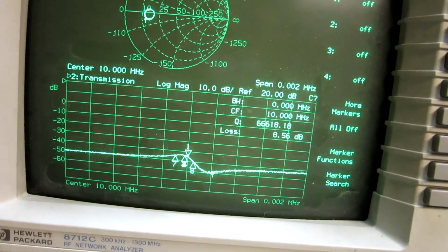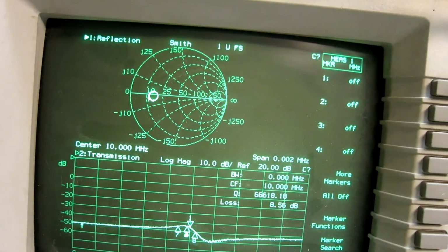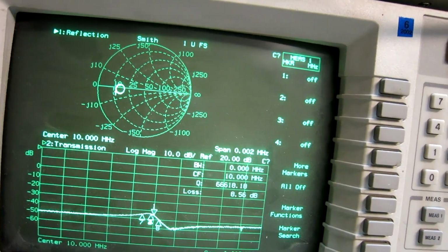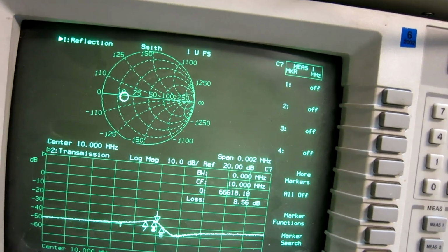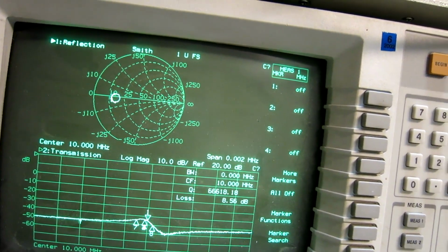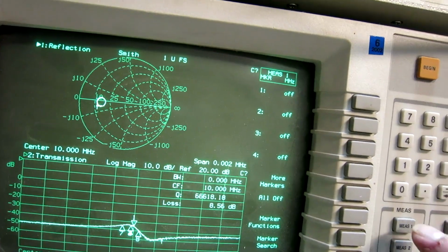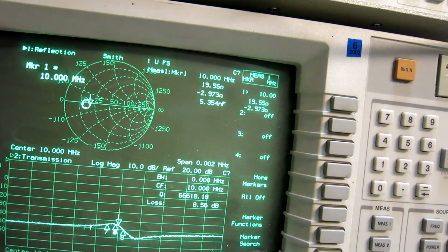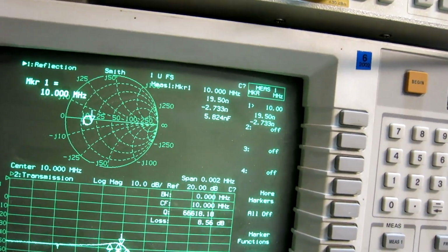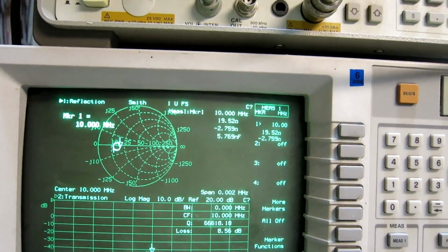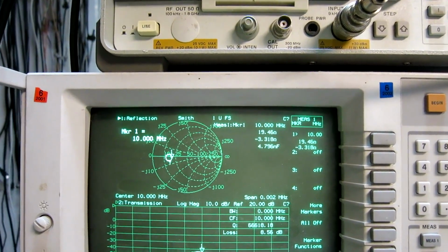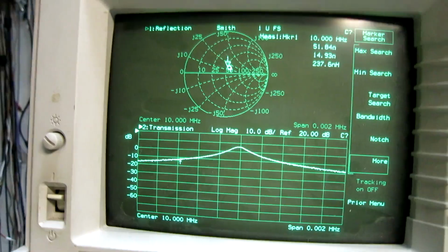The signal is very weak and the impedance on the source is now about 12 ohms. This is much better than before, although on the resonance it's a little bit higher. Let's see, measure 1 and marker. It's 20 ohms, 19.5. So I need to connect 30 ohms in series to get the 50 ohm signal source to measure the noise floor that I have at this point.